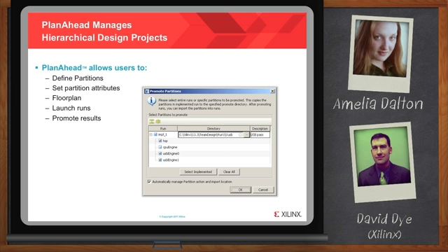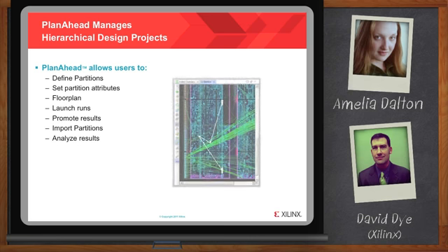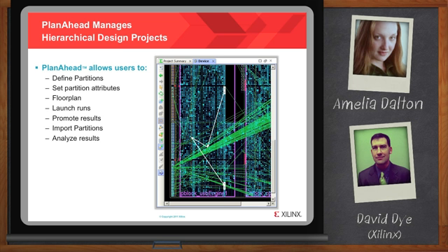Promoting a run for reuse saves a copy of that design and ensures that further iterations on that configuration don't overwrite your golden results. Now, for later runs, the Specify Partitions window lets you pick which modules to reuse and from which prior run. Preservation levels can be set there. And finally, at any point, there are a host of analysis tools to let you examine results and check timing. PlanAhead gives access to many integrated views of your design throughout the synthesis and implementation process.